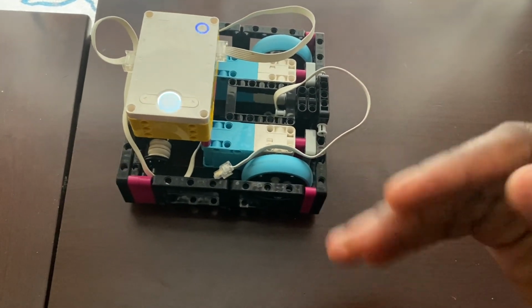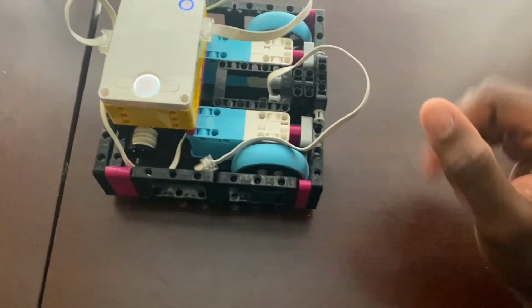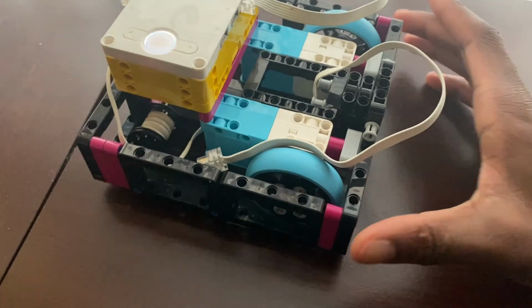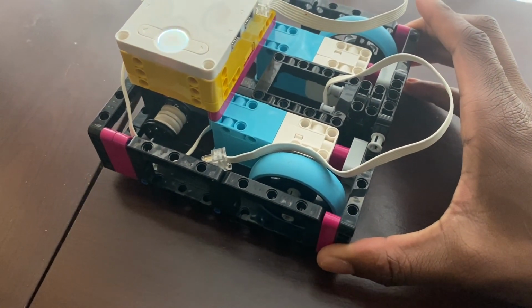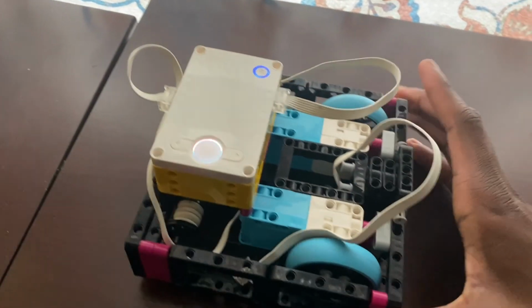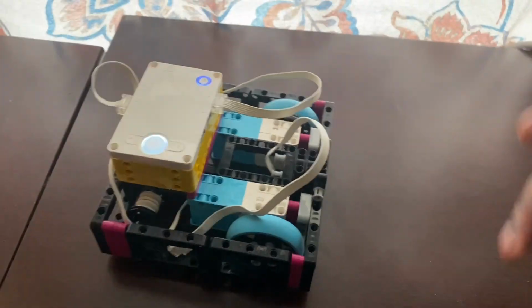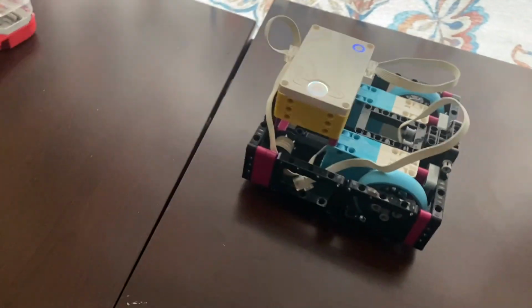You can see it's not exactly getting to 90. It went past 90, and now it's just fluctuating. It's not getting to a resting point, so the program is still running. It's not stopping. And if I hold it and try to turn it swiftly, it might stop. But that's why you don't want too high of a number, because it won't get to a resting point. It's still thinking it needs to have a lot of power to turn it, which in reality it doesn't. So that's why we need it to be smaller.